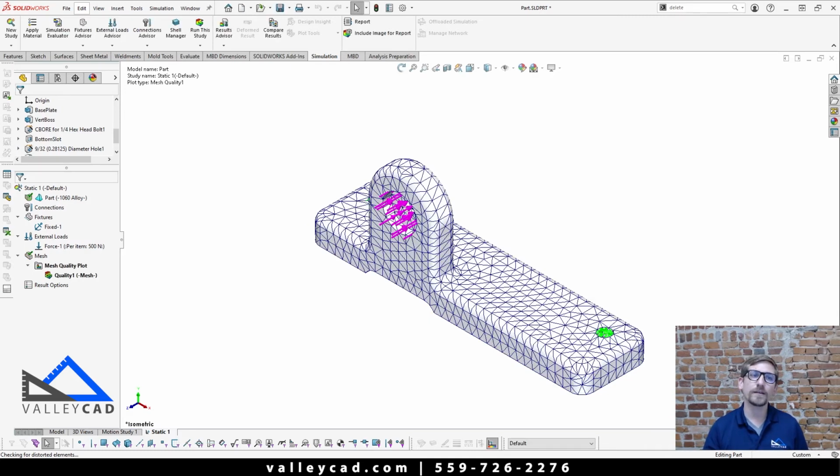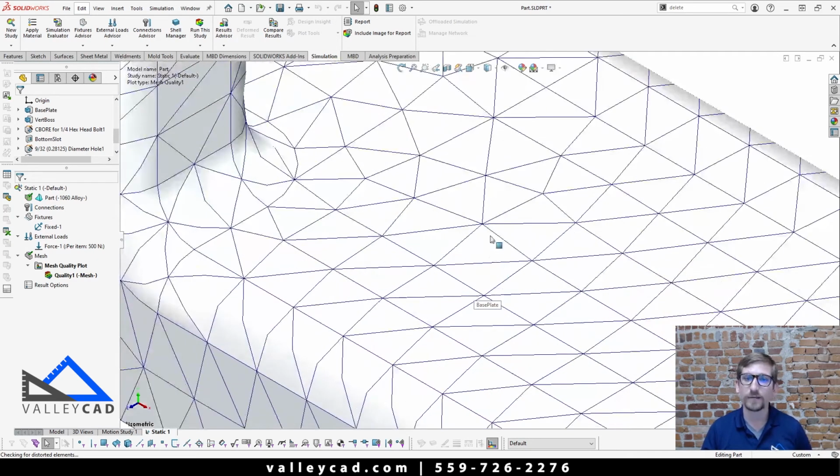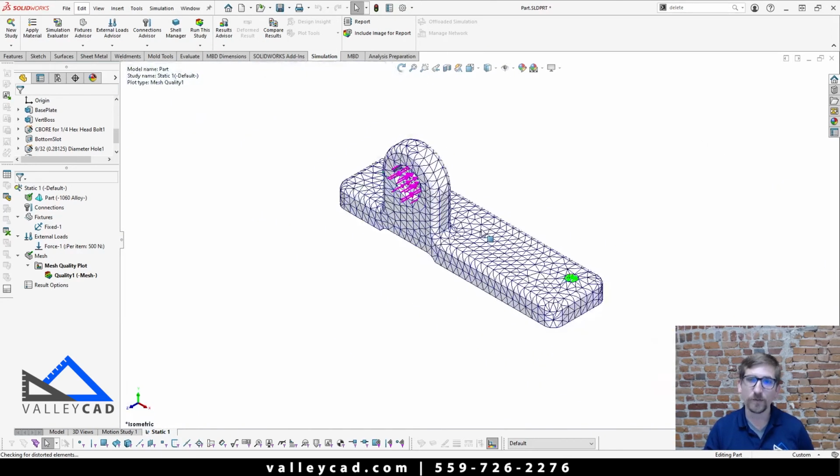As it's doing that, you'll now see that SOLIDWORKS came in and made all these little triangles on my part file here. These are all your facets. And like I said, where all those triangles connect, those are now called nodes. Since we just kept it at about 50%, it's a pretty good average here.